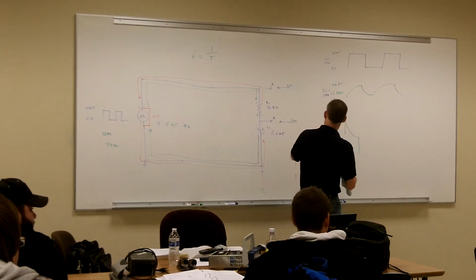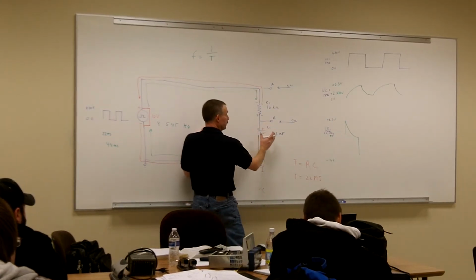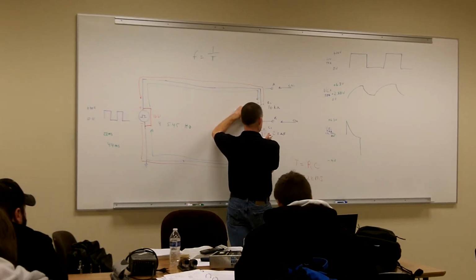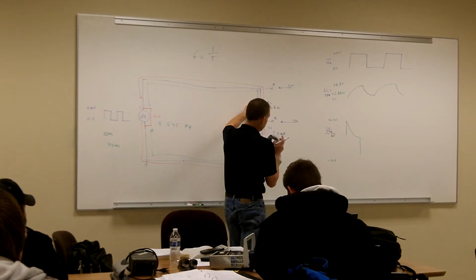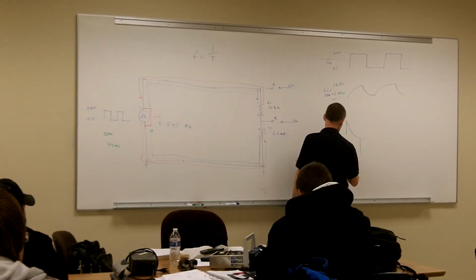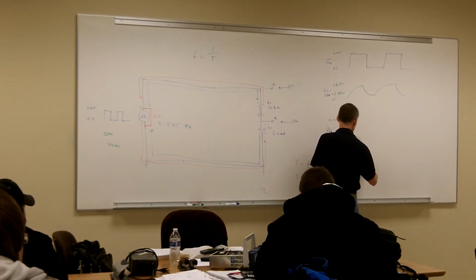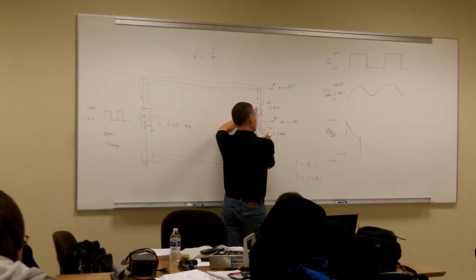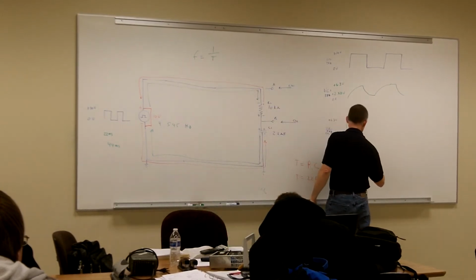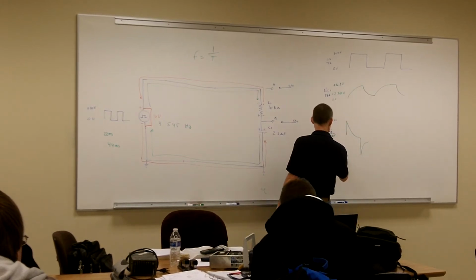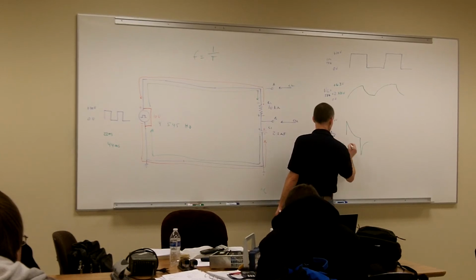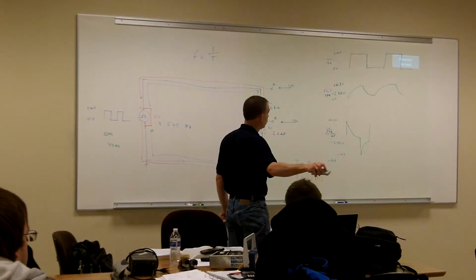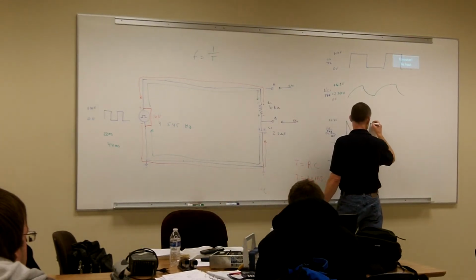Then the polarity is going to switch. It's going to start out at 2.331 volts, and once the capacitor becomes the source, the voltage across R1 is going to go to a negative 6.3 volts. Then the capacitor is only going to discharge to 2.331 volts. Since the polarity changed across it, it's going to change to 2.331 volts, then go up to 6.3 volts, and just start repeating the cycle again.